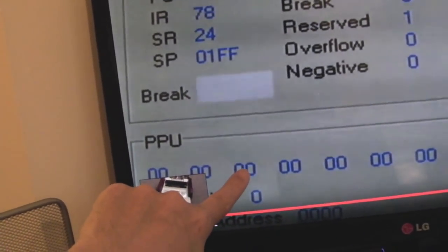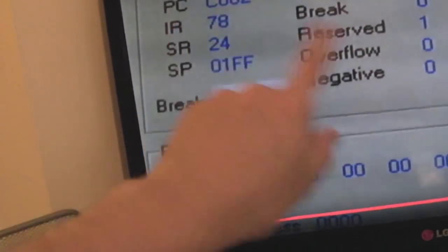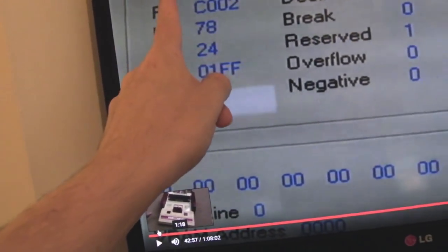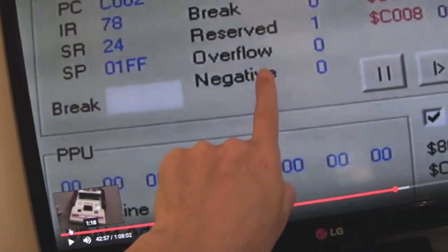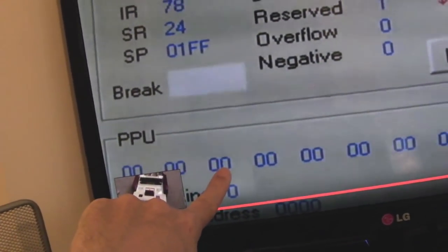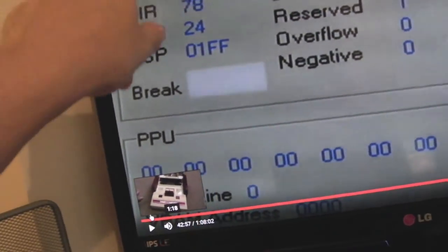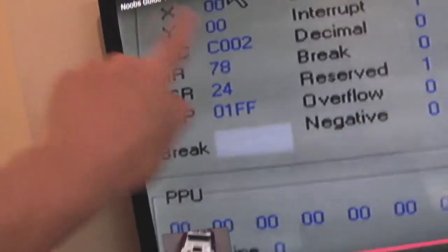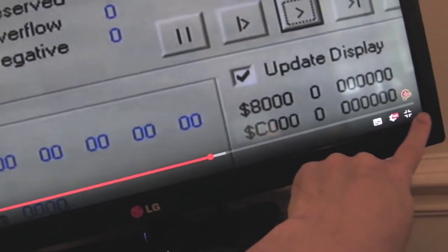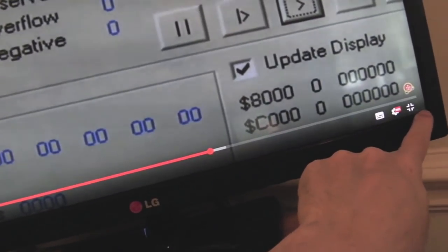And I'm guessing that the negative value goes in there, and when it does that read into, I can't remember what it was reading, was it reading into the accumulator? I think it may have been. The negative flag will be set because of that negative value. It's probably like FF or something goes in there to indicate that it's got to the V blank scenario and gone back up here, and that takes a period of time when it hits the V blank from the end of this final scan line.